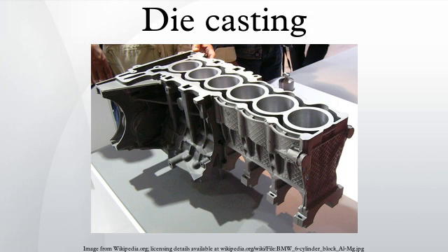Die casting is a metal casting process that is characterized by forcing molten metal under high pressure into a mold cavity. The mold cavity is created using two hardened tool steel dies which have been machined into shape and work similarly to an injection mold during the process. Most die castings are made from non-ferrous metals, specifically zinc, copper, aluminium, magnesium, lead, pewter and tin-based alloys.